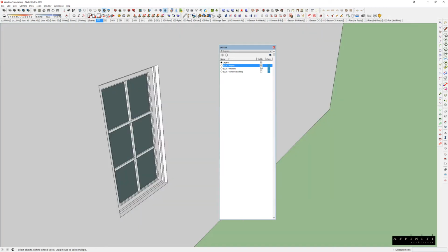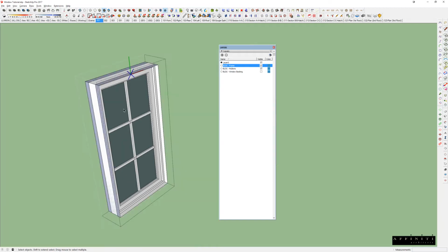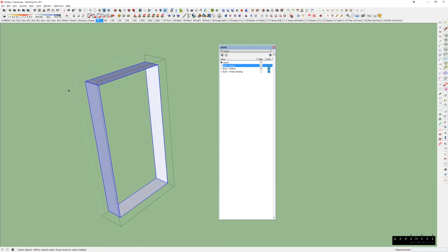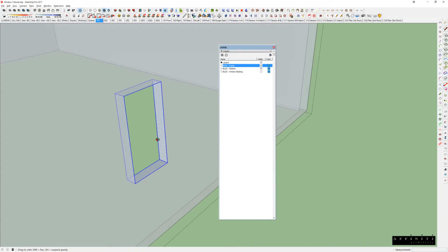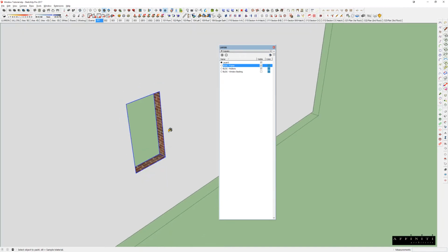the reason why I would turn it off is because you essentially are overlapping geometry. Meaning if I go into my window group, you see I have this geometry, which is identical to, if I go into the wall, this geometry. And for the most part, it's really not an issue until you get into renderings and or adding in materials. And I'm going to pull up just a brick material real quick to show really what's going on.